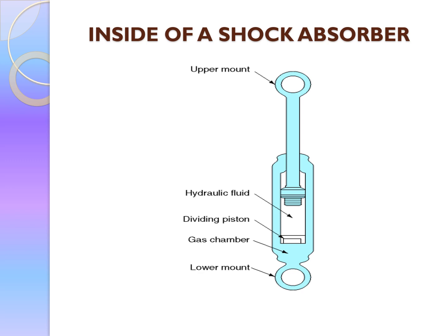And during rebound, the pressure in the compression chamber falls below that of the reserve chamber. As a result, the compression valve will unseat and allow fluid to flow from the reserve chamber into the compression chamber. At the same time, fluid in the rebound chamber will be transferred into the compression chamber through the inner piston holes and the rebound valve.